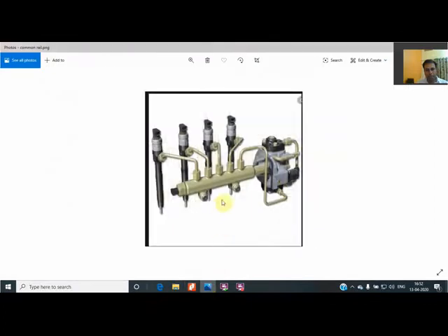They are getting the fuel supply from the common rail itself, and these injectors get a current, means the electrical signal is given to these injectors, and as they get the electrical signal, there is a solenoid type mechanism which gets activated and they work.